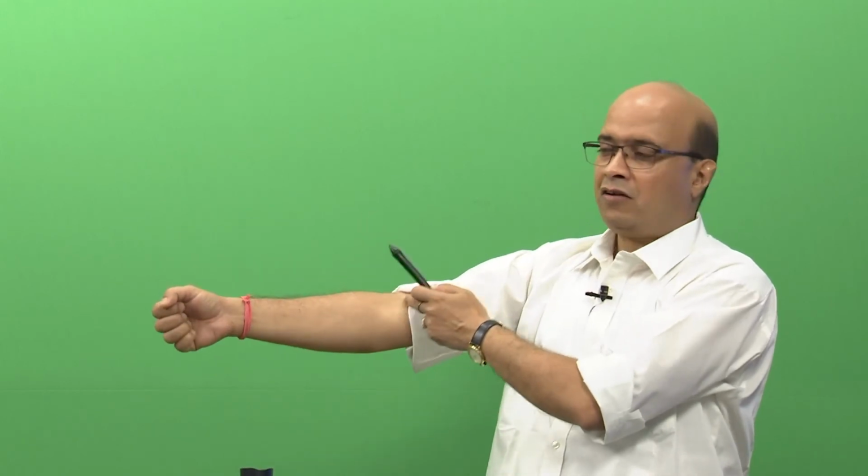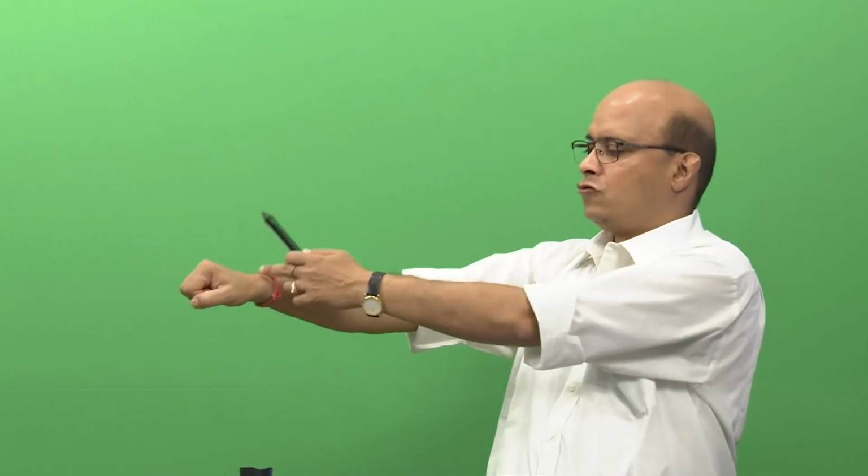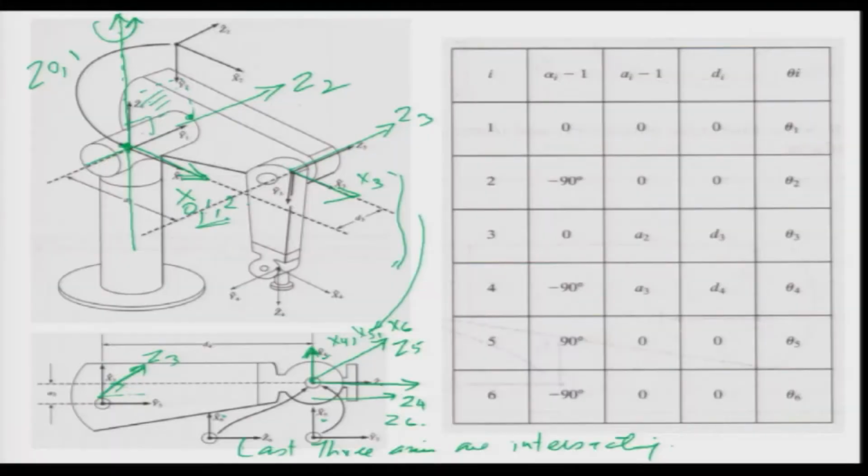from here. Now, in the human arm, we have 3 degrees of freedom, because this is a ball and socket joint. So, we have 1 axis, 2 axis, and the 3rd axis. Okay. So, we have 3 degrees of freedom at this joint. We have 2 at this joint, which can close like this and can rotate. So, 2 degrees of freedom here, and 2 more here. So, this is my pitch, and that is my yaw. So, I have 3, 2, 2, that is 7 degrees of freedom. So, there are some differences with this PUMA robot, which we should keep in mind.